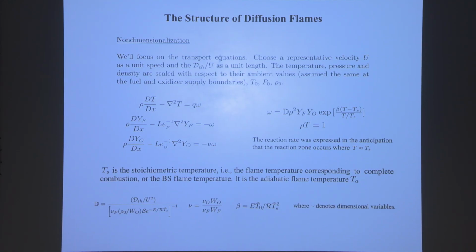Yesterday, if I can summarize what I did, what I tried to show you on the diffusion flames, I first showed you that if the Lewis numbers are equal to 1, for unity Lewis numbers, then one can solve the entire problem in the large Damköhler limit, namely when everything is consumed, or maybe the limit, if you like, of complete combustion, simply from the coupling function.